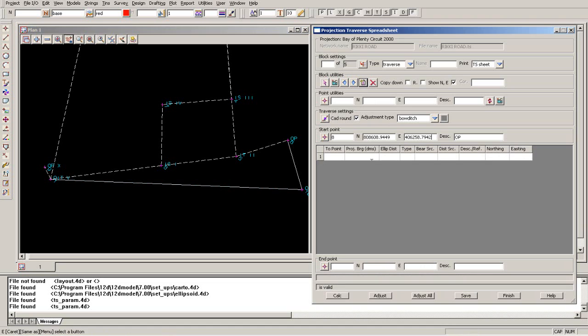We're going to start at 8 there, and we're going to go to our new point, which is peg 2, and that's going to be 263 degrees 2350. We're going to go 55. Now this is a boundary, or I just show it as a calculation in this case, but it's a road boundary. There's the ability to show it as that, but this will just give it a different line type, which is pretty fine by me. Peg 2.